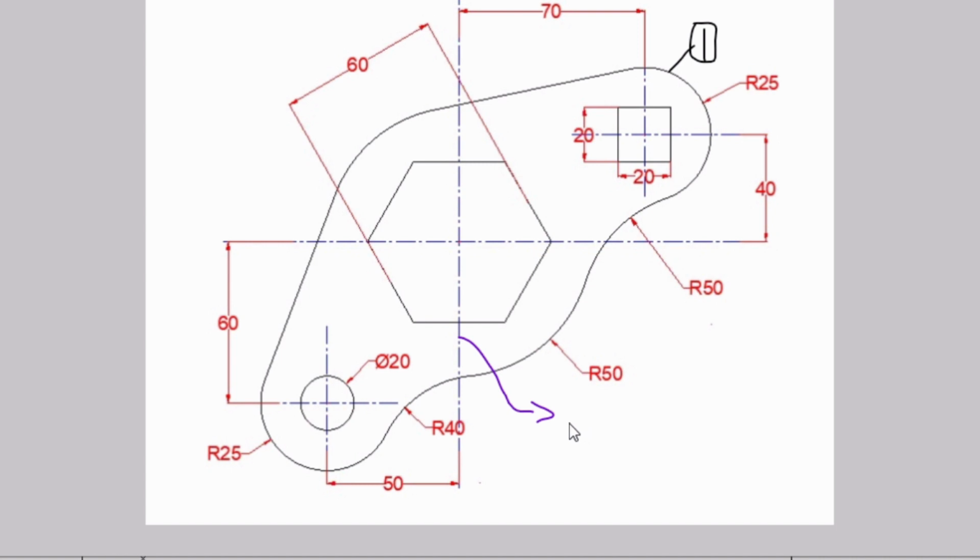which represents the construction lines, the lines that we use to construct this drawing, which we use as center lines, you can see. And that center line is not only a different color, but also a different line type. You can see the center line looks like a big line, then a small line, then a big line again. It's a chain line with alternating big and small lines. That's a particular engineering standard that we use when we are marking a center line. So we have that type of line available here.